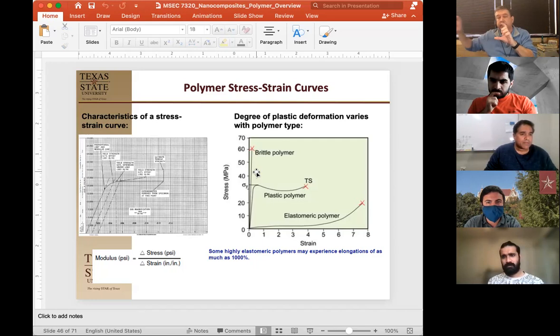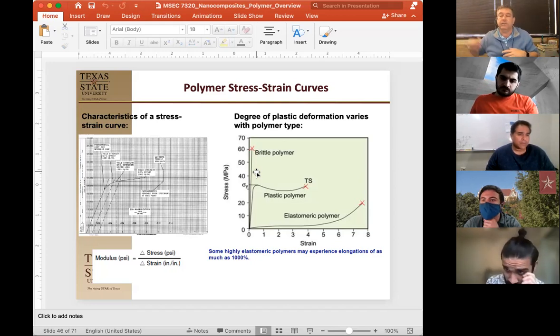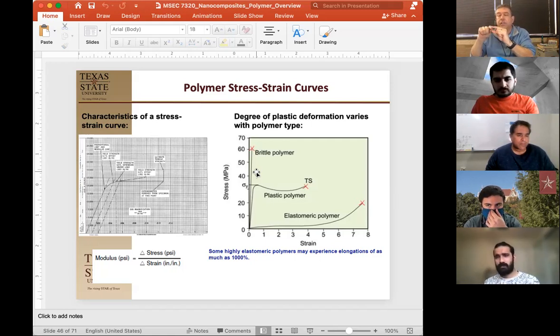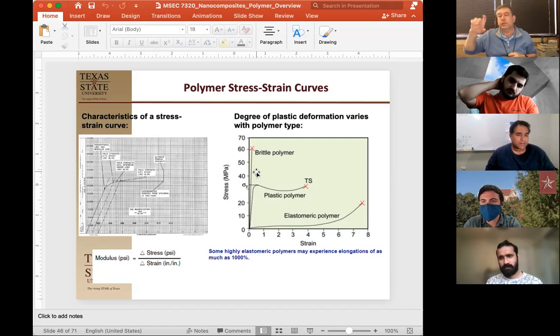So, and then there's several different types. You can do an ASTM A, B, C, and D. And so you can get different durometer readings for each of them. Most of those are force and the shape, or whether the penetrometer is domed, pointed, or flat. And so you can change the different penetrometers versus the different forces. And so that's what the different ratings mean.